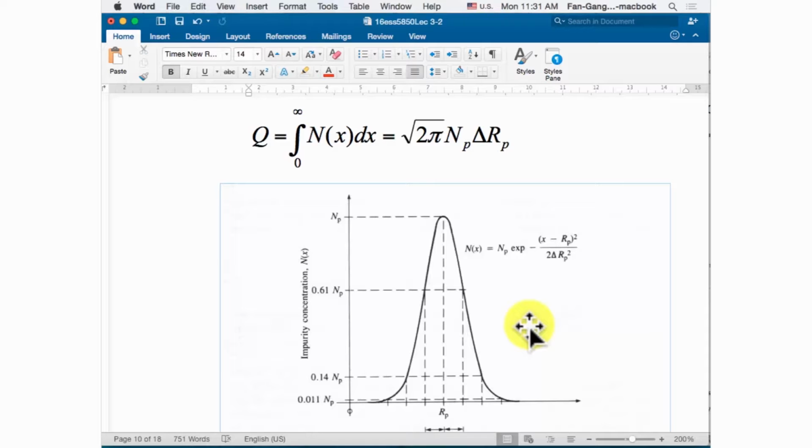So the final profile, maybe it looks like you have a more concentration here, and the surface is a bit lower, high concentration here, and even low concentration at the interior. It's different from diffusion. Diffusion always has a high concentration on the surface. But this one, you can control the high concentration not on the surface, maybe inside some kind of depth of the material. Okay? So this is a good thing of implantation.